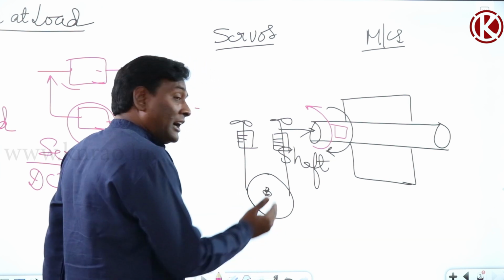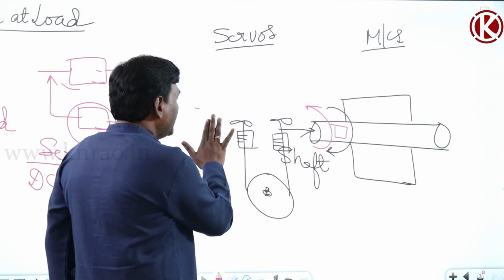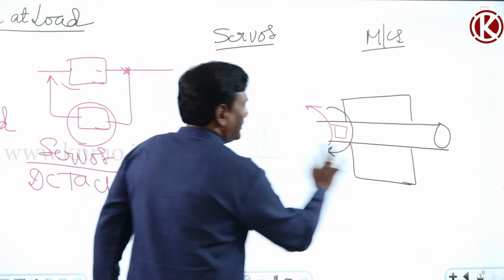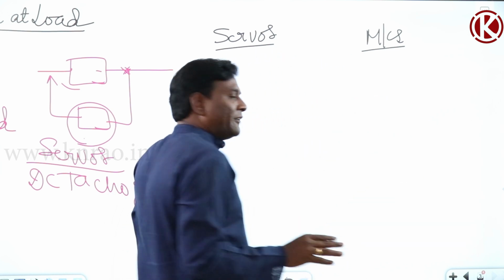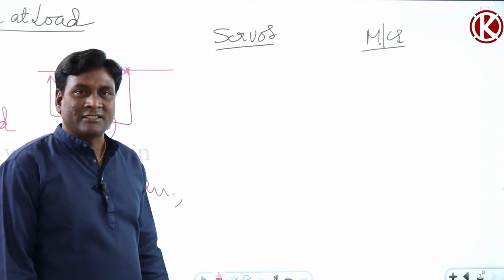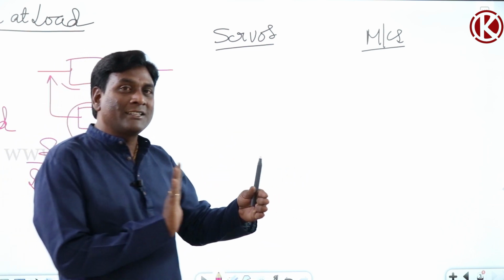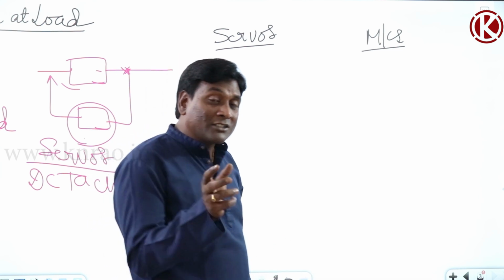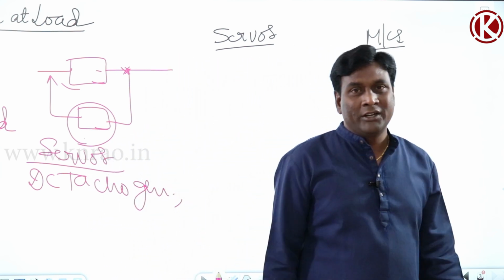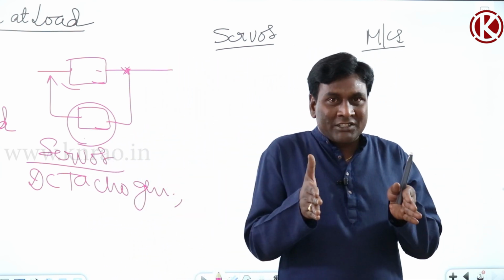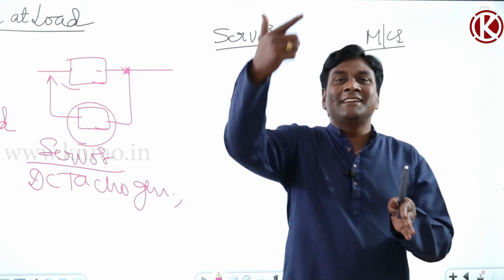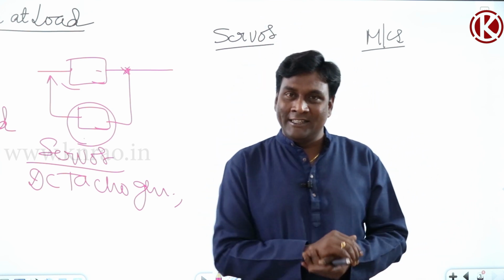Of course, I am coming back. Now, if you think of the shaft as the costliest part in a machine, in order to reduce the length of the shaft such that the cost of the machine will be reduced, we will increase the radius of the rotor.